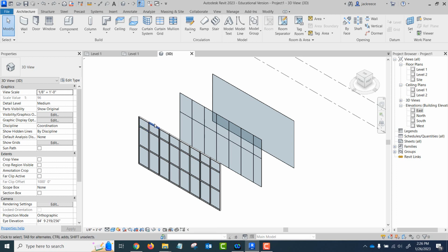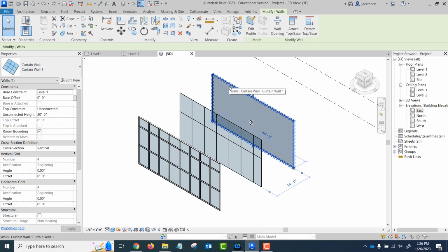We're going to go into how to create and edit these things, okay? But at its basis, you pick which model you want to start with. If you were to do a lot of storefront or curtain wall type work, you would pick whichever family you want, which most likely would be the storefront type family, and you would duplicate it and create your rules that you use most often so that it's kind of a default wall type. Okay, so let's look at curtain wall 1, and let's go into edit type.